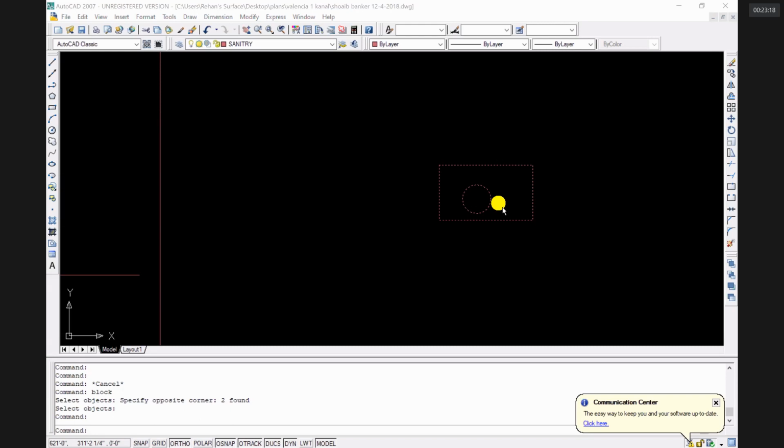103 is asking, for the boundary wall, should we draw a one-sided foundation or is it up to us? Yes, good question, 103. Basically, foundations are under the surface. Now, the problem is that you cannot go outside your property limit. In all cases, boundary walls are constructed at the property limit. Property limit means the line after which your property ends.